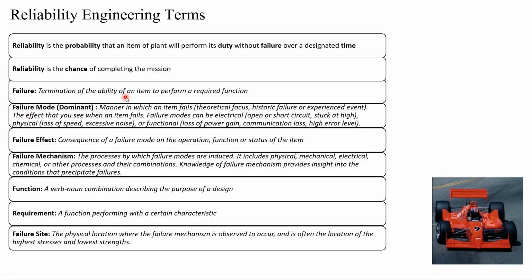Failure modes can be electrical (open or short circuit, stuck at high), physical (loss of speed, excessive noise), or functional (loss of power gain, communication loss, high error level). Failure effect: the consequence of a failure mode on the operation, function, or status of the item.